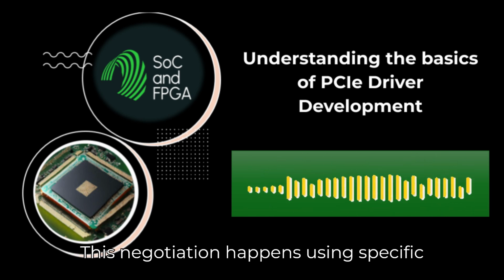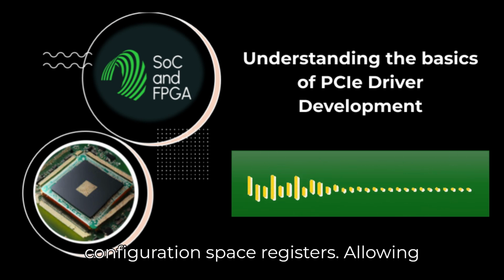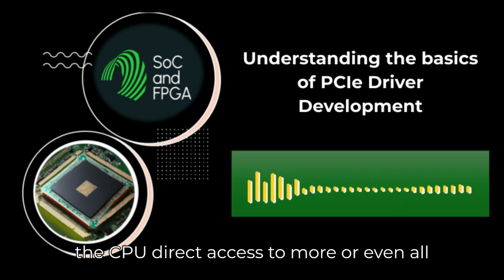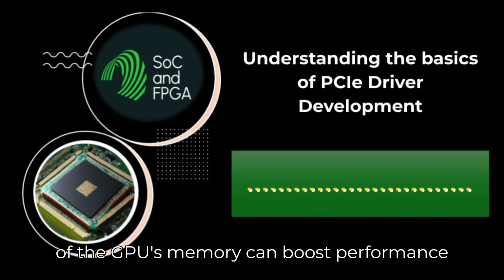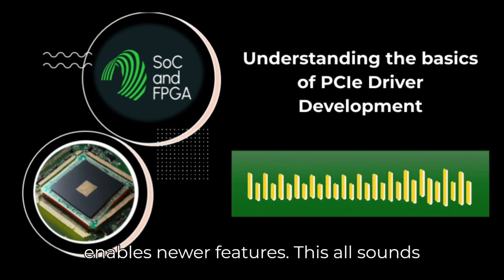This negotiation happens using specific bits and fields within the PCIe configuration space registers. Allowing the CPU direct access to more, or even all, of the GPU's memory can boost performance in certain games and applications. It's a good example of how the config space enables newer features.